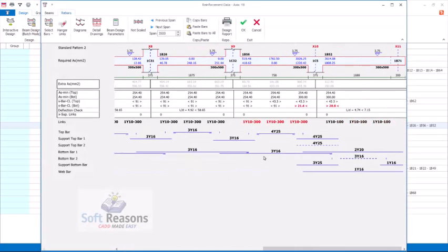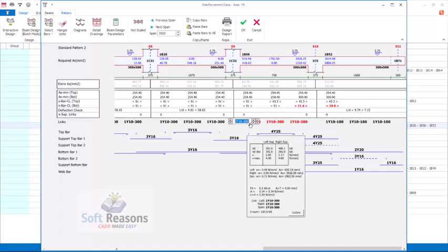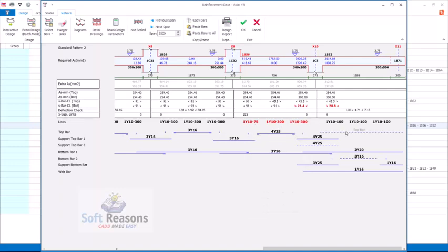If you check very well, you can notice that the links, the shear reinforcement has failed. Okay, failure is at the shear reinforcement. And what could cause a shear reinforcement to fail is the depth of the beam not being enough for the load it is carrying. It will cause the shear reinforcement to fail. All right, and here the size and the spacing of the bars are too narrow. That's why I'm having this red sign over here. All right, because we are having 4y25, 4y25, so it is too narrow.